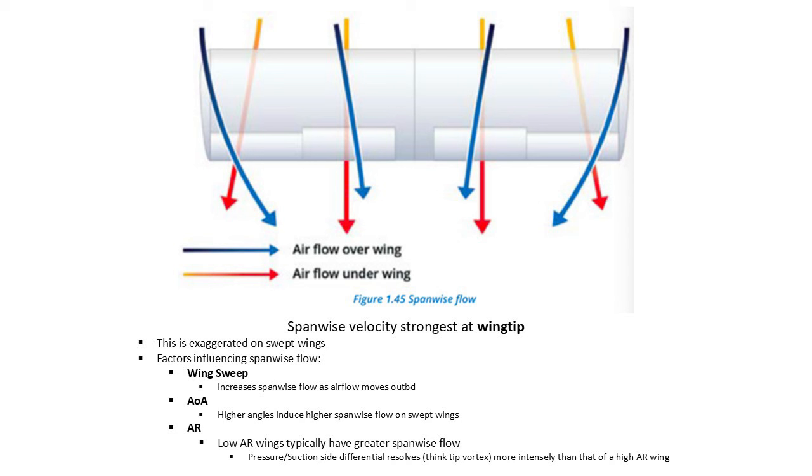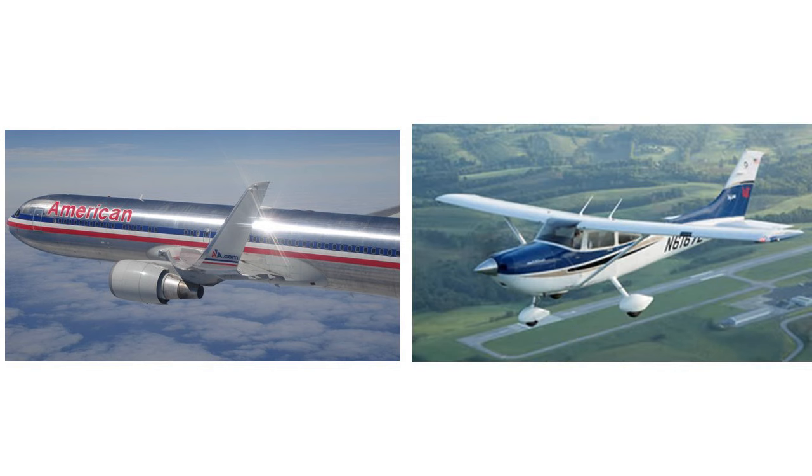Now, as any good engineer will always point us back towards the pay-to-play nature of aerodynamics and aeronautics, think, what are the consequences of a proper wing design that either decrease induced drag by increasing the main wing aspect ratio, or alternatively by just the addition of proper winglets? Okay, let's say we designed a perfect winglet for our design flight conditions and we've minimized the weight addition due to the increased wing root structural demands. Why don't we see winglets everywhere then? If engineers can dedicate time to generate the perfectly optimized winglet, why aren't there winglets on every plane?